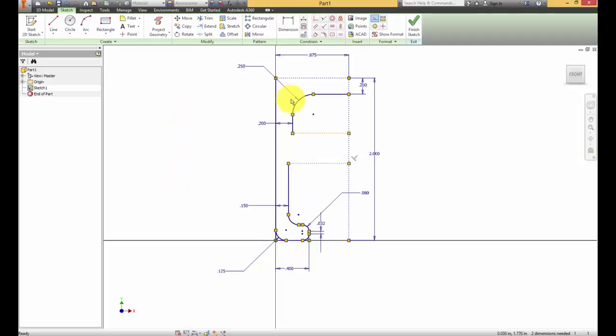What I want to do now is actually draw this line, or I can go ahead and actually make this line. I can put a dimension. This line is going to be 0.6. Now what I can do is I'm going to have an arc that's going to go from here to somewhere up there, and I'm just kind of putting it on there, and I'm going to dimension that arc.